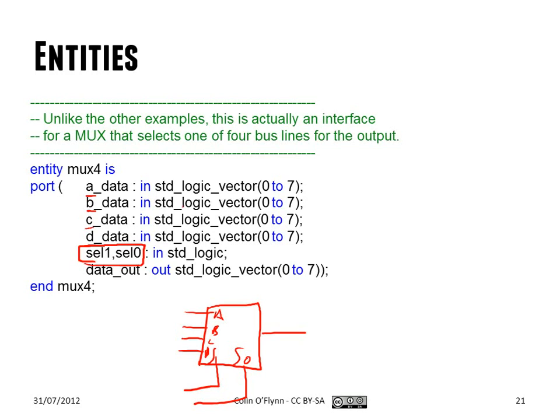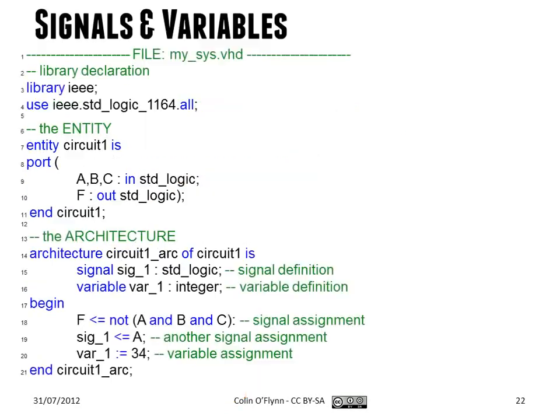This vector is just 7 wires bundled together. So each of these is actually 7 wires, but it doesn't matter. When you pick A, it's just those 7 wires are all going to be directed to the output A. So that's this standard logic vector that you'll see around. So here is a typical-ish VHDL file.